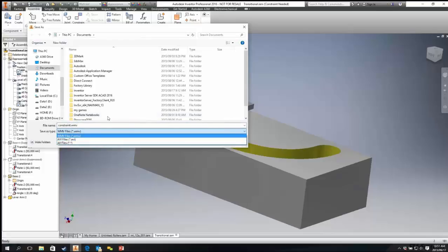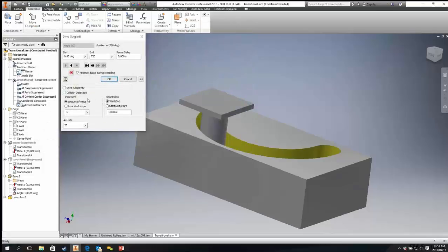You can go modify the quality. But here, repetitions, we can say how many times we want it to do it. So if I just rotate this by 45 degrees, which will be pretty quick, 4 degrees of change, you'll see if I do 4 rotations, it goes from the start to the end and continues like that. If I push play, it'll jump back continuously like this, unless I say start, end, start, which will then allow me to jump back from the end position to the start position. Okay, we have basic things we can modify like this.